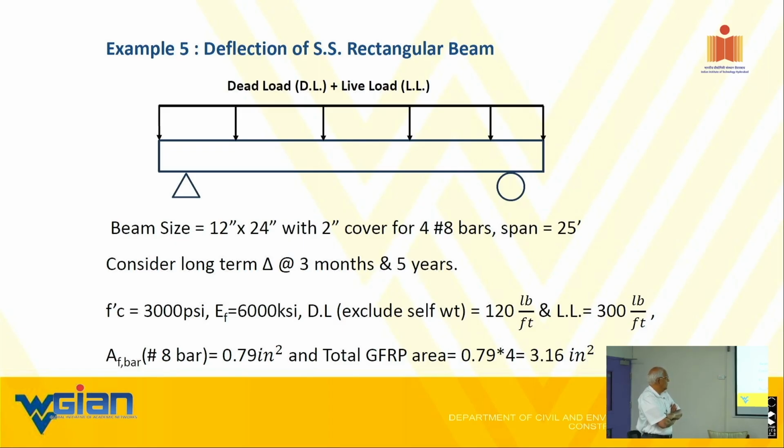Here we are talking about a beam 12-inch by 24-inch depth with a 2-inch cover, 4 number 8 bars, that's about 0.79 square inch each, and the span is about 25 feet. Consider long-term deflection at 3 months and 5 years.